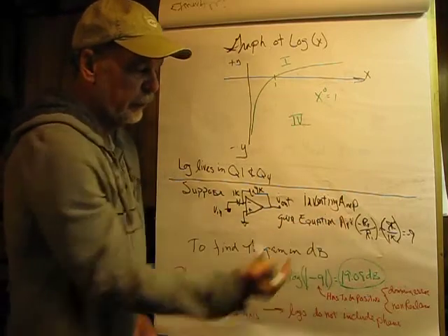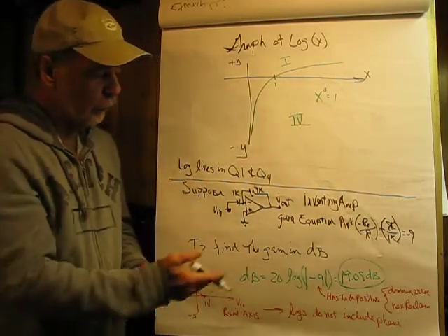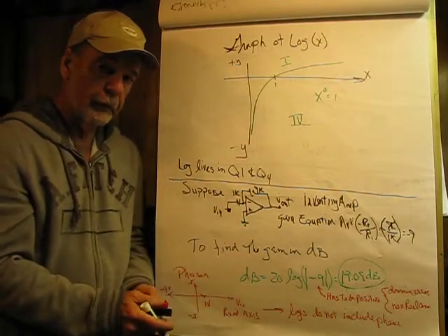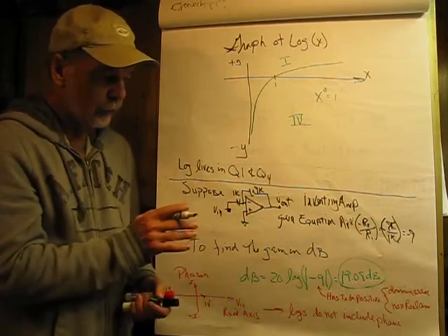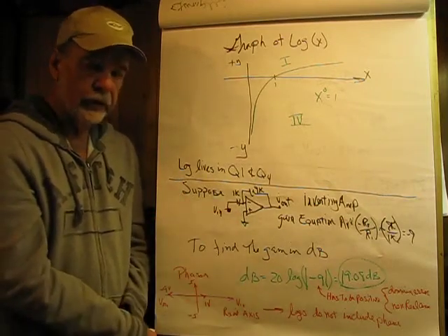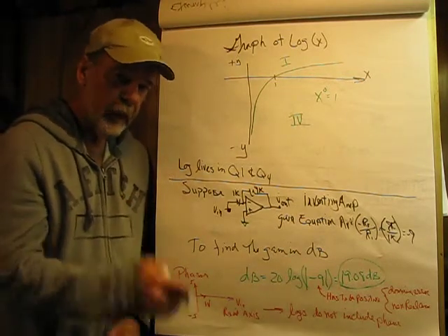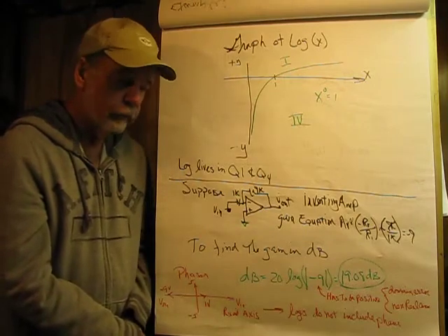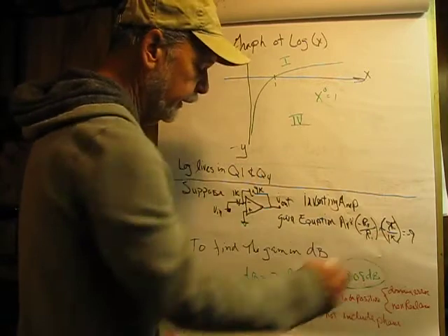I really could put an equals, because with a contemporary operational amplifier, the gain is so closely determined by RF over the input resistance RI that the equation is just about perfect, totally swamped by the tolerance of the resistors. So if we work that out, we get a gain of -9.